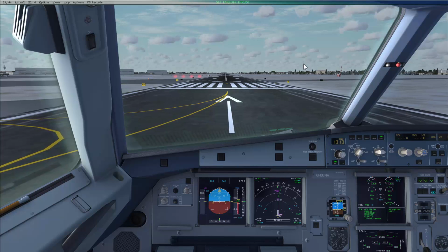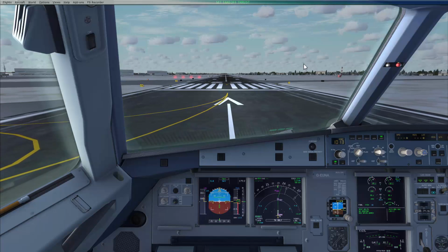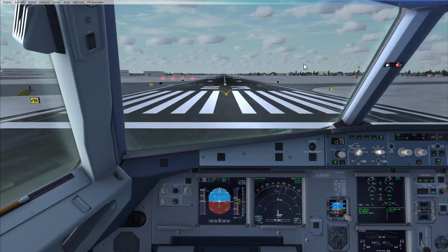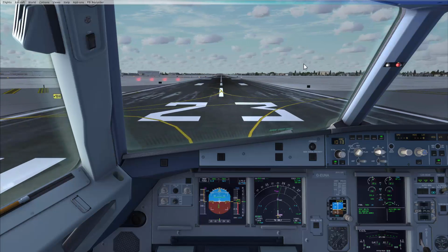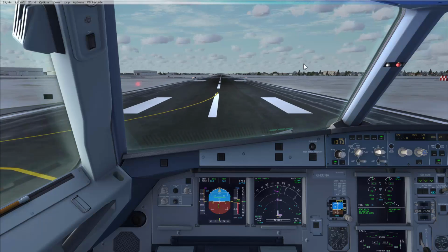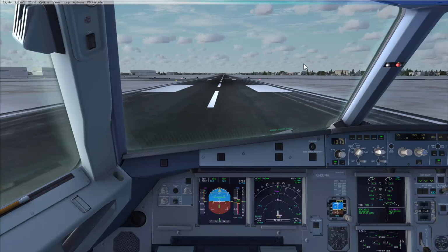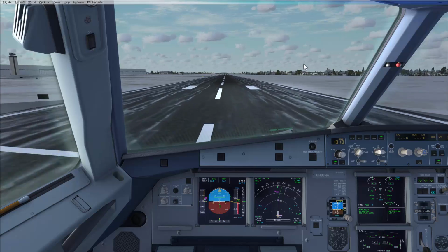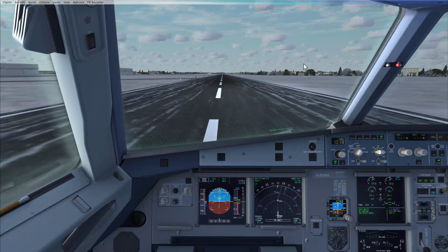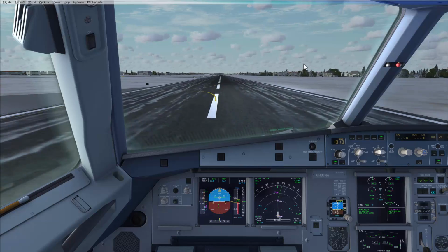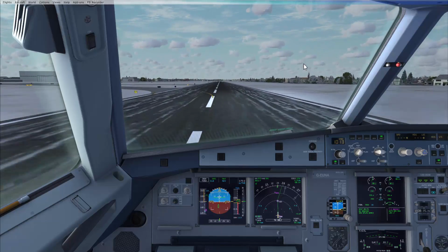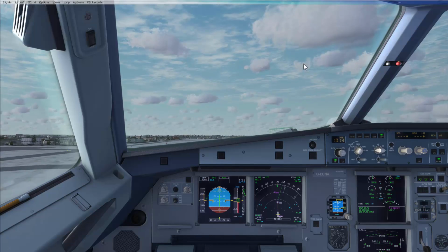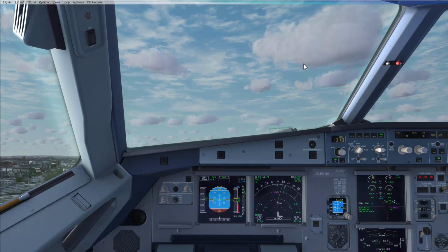On runway 23, brake off. On runway 23. And full throttle forward. Man, TOGA, SRS and runway. Check. Power set. Apply a bit of left rudder here to keep us on the centre line. 100 knots. Checked. V1. Rotate. And up we go. Positive climb. Gear up. Gear up. Navigation. Check.